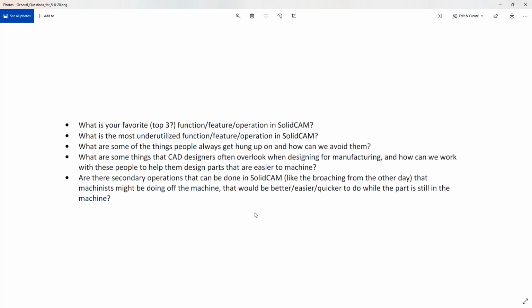And that is corner radiuses and tool possibilities. I've done some designs where, when I was new, I didn't realize that that corner radius is impossible. A tool doesn't exist with that radius, or there really is no way that a tool is going to reach there, or the angle that the tool is going to take on your 5-axis machine is not possible on your machine. The machinist either can't see it, or there's not enough reach for the tool. So that's what I would say.